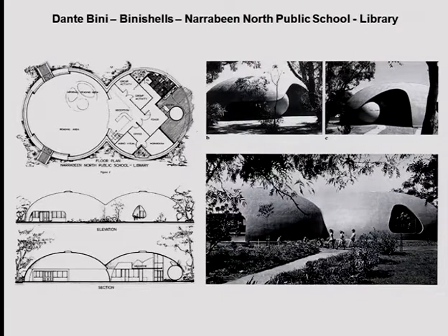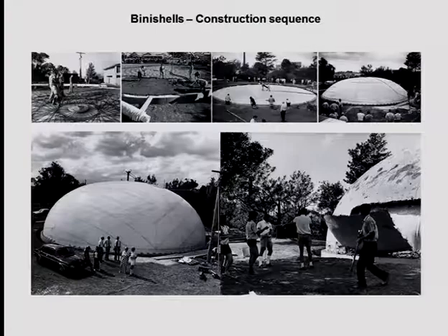Most of them are in New South Wales, but the technique was fast to construct. It was able to build these types of structures in 13 to 14 days. So it's pretty fast. So you see here what happens. They place the reinforcing rods in a radial way within some springs just to keep them in position. So the springs have the same property of a bar chair. Then they pour concrete on the flat surface, so rather easy. And then they place a membrane on it to cover it. Of course, there was already a membrane underneath.